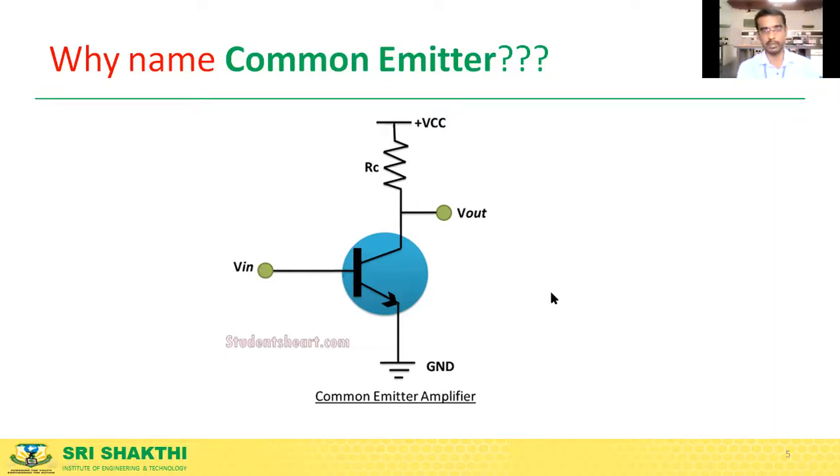So that is the common collector. Where you take the output is going to decide whether it is common emitter or common collector. If you take the output at the collector terminal, it is called common emitter. Here the emitter is common between input and output through ground.